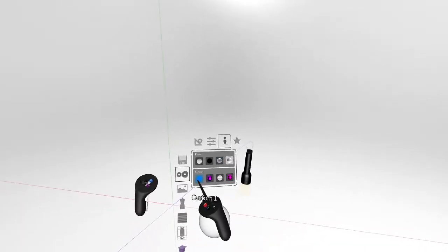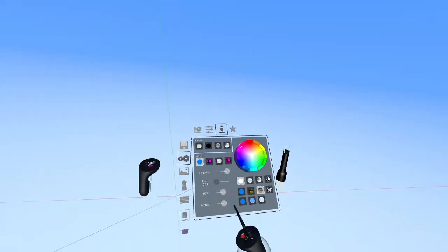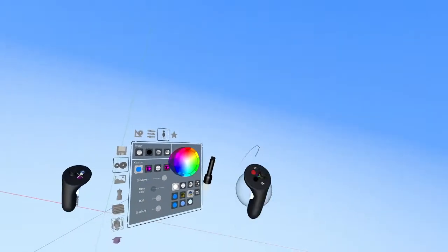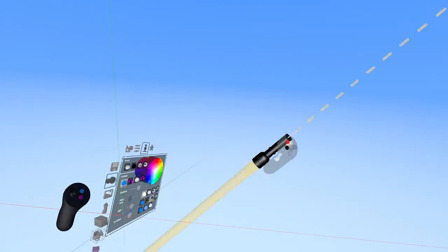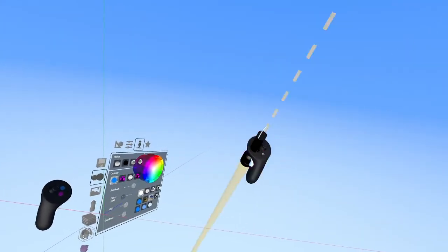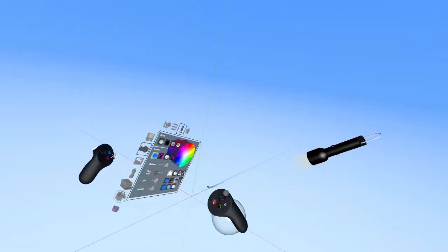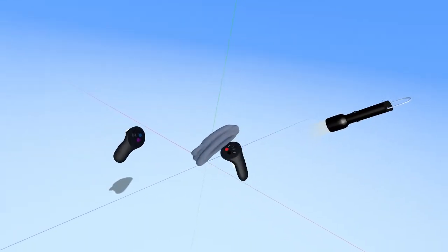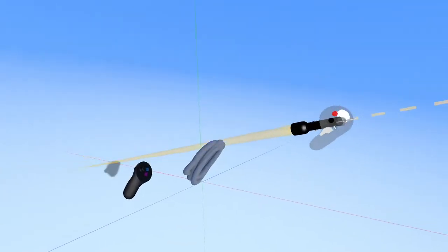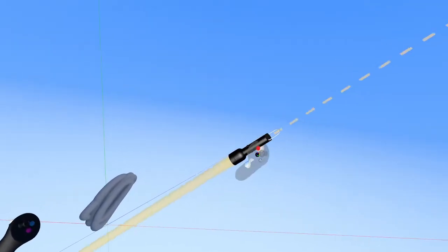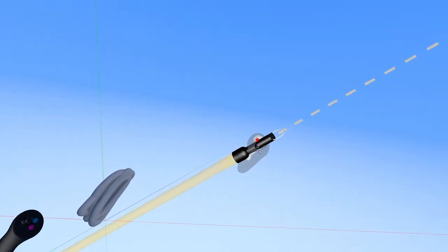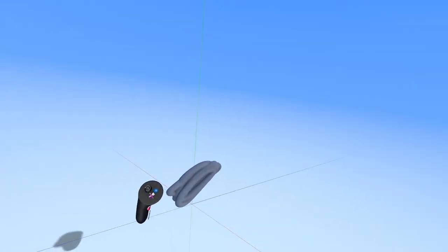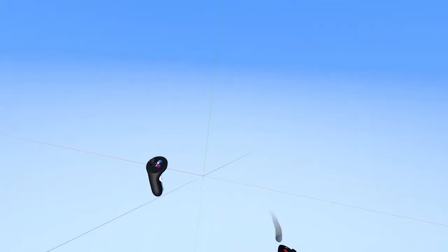Now, there's the presets above here that you can toggle through and select, and these are pretty great. But if you want a little more control, we can come down here to Custom, turn on Gradient, and I like this sky tone gradient that goes all the way down to a light blue, so we're going to stick with that. And then if you did want to adjust the lighting direction, you can grab the flashlight here, choose a direction for that lighting. It's a little easier to see if we actually sketch something in here, so you can see how that's affecting the geometry. And then once you have that selected and you want to get rid of this flashlight, just grab it, hold it, and delete it with the red button, the same way you would delete geometry.